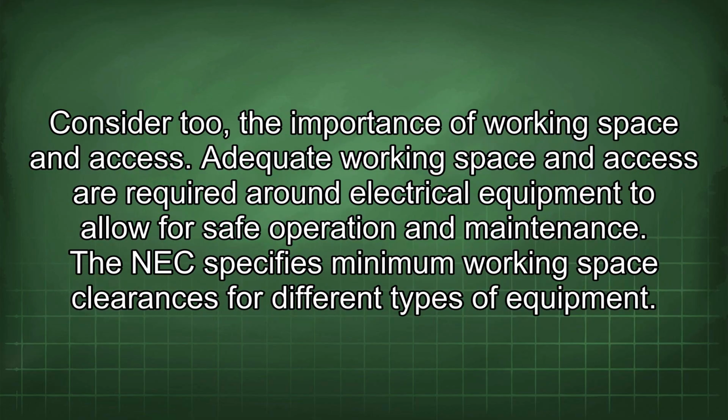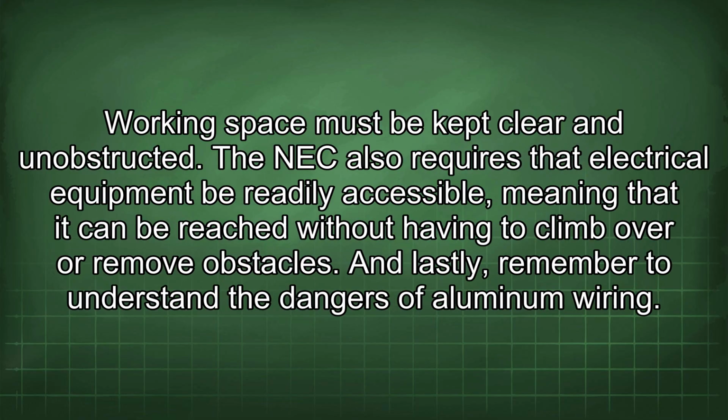Consider too the importance of working space and access. Adequate working space and access are required around the electrical equipment to allow for safe operation and maintenance. The NEC specifies minimum working space clearances for different types of equipment. Working space must be kept clear and unobstructed. The NEC also requires that electrical equipment be readily accessible, meaning that it can be reached without having to climb over or remove obstacles.